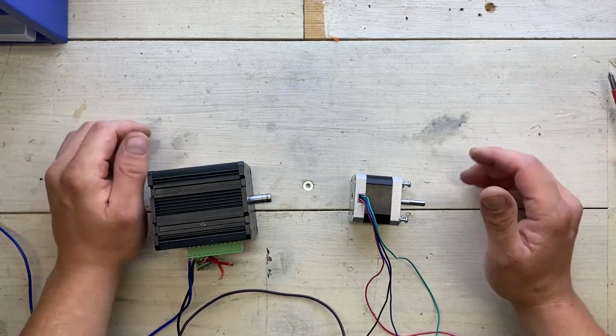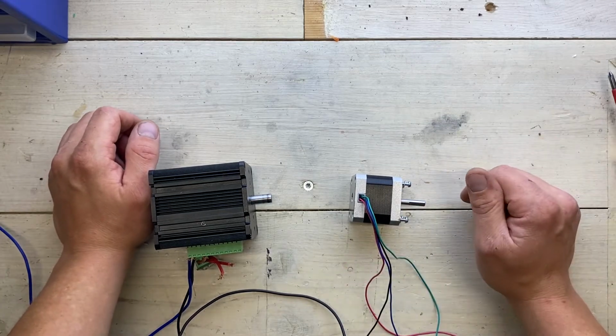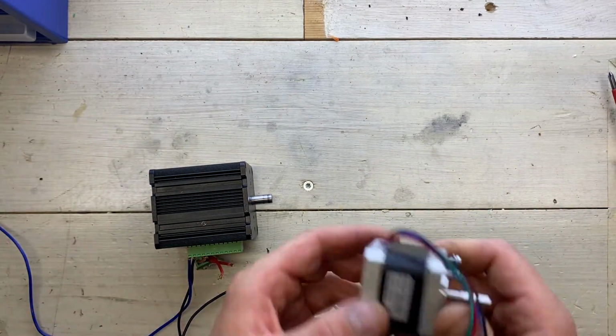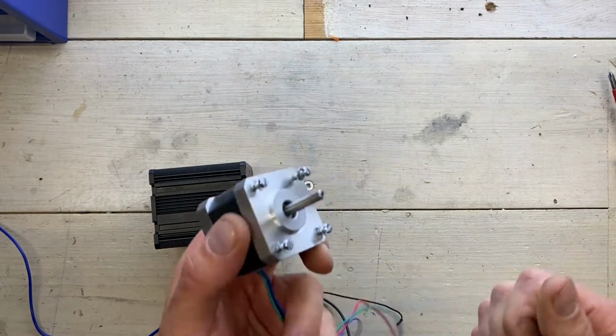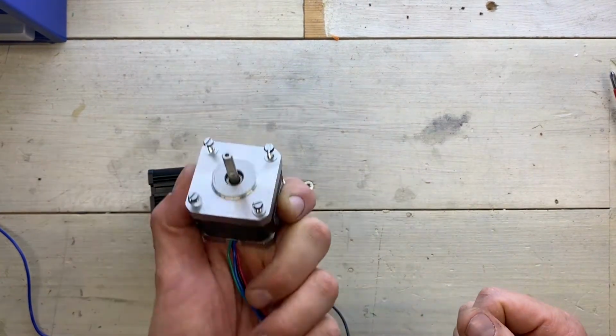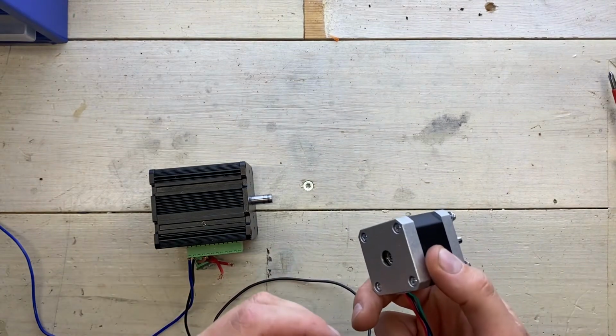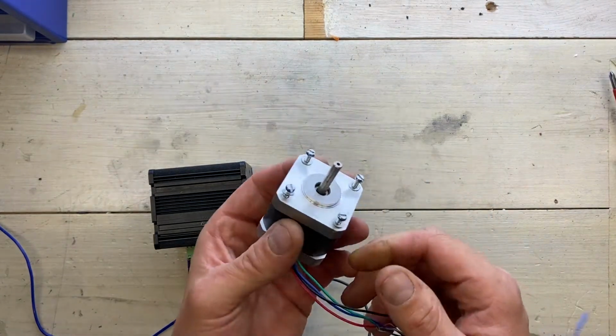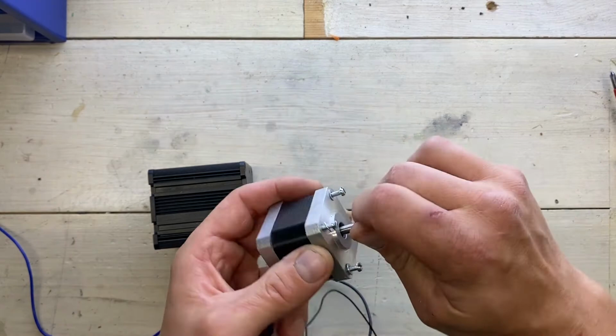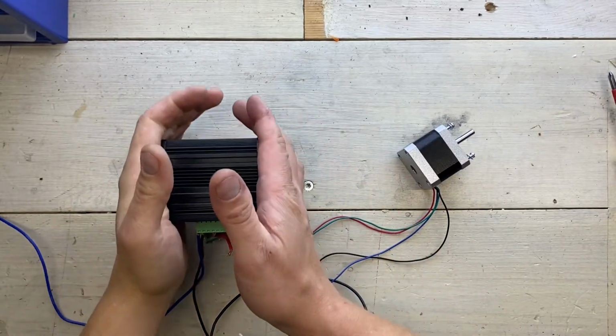Now, if you're building a homemade CNC router like I did, steppers can be extremely accurate, cheap and easy to use, and there's absolutely nothing wrong in using them, but you have to know their limitations, such as that they lose steps at high speeds and have the most torque at low speeds. And servos are the opposite.